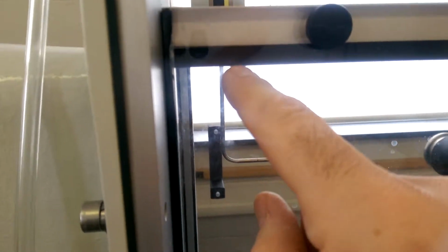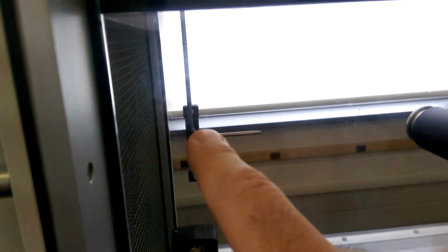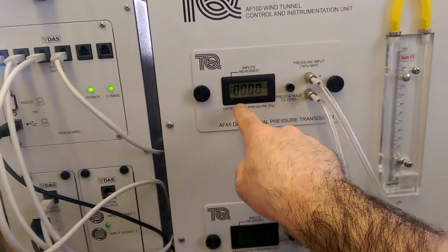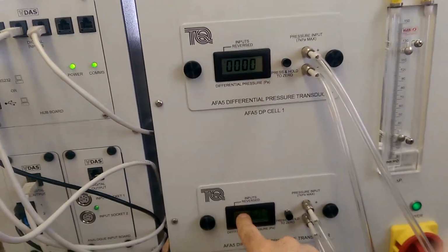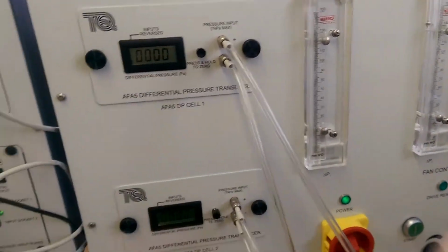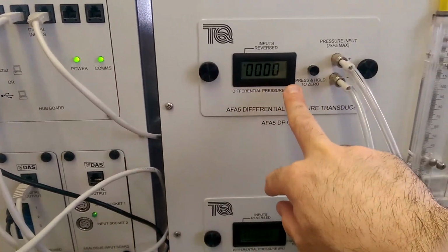So what's going to happen is that you're going to move it from a top position, move it down until you start just getting into the wake. That should be a point where this velocity starts to change, to a point that this pressure is slightly below this pressure. Try to position the pitot tube such that these two pressures are approximately equal.